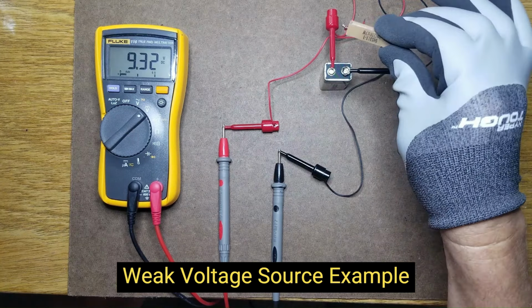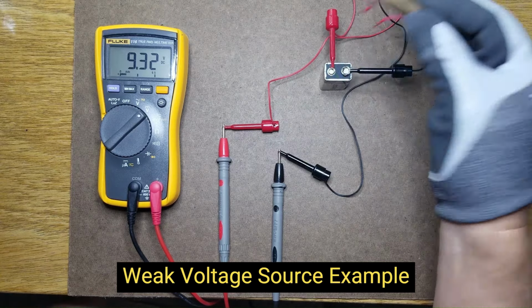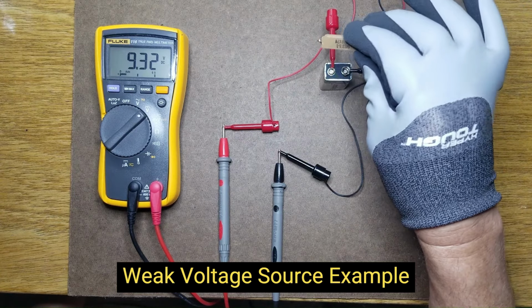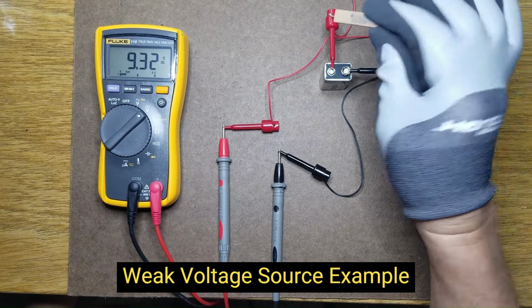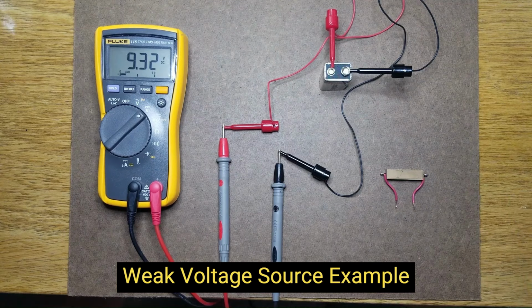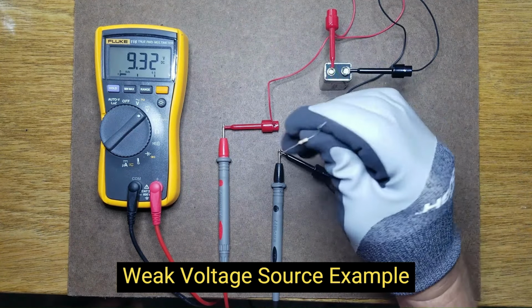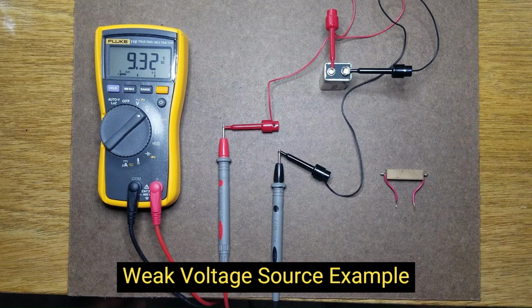Note that this is a 7 watt resistor, because if you were to have 1 amp of current flowing through a 10 ohm resistor, it's going to dissipate 10 watts. So this is a 7 watt resistor. It's going to easily be able to handle it for a couple of seconds. What you don't want to do is use a small resistor like this, because you will burn yourself if you do that. And again, don't try this at home.